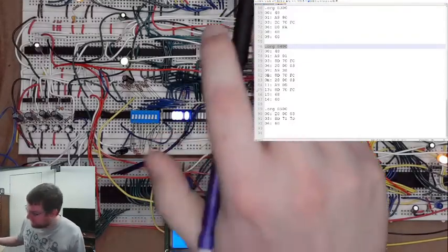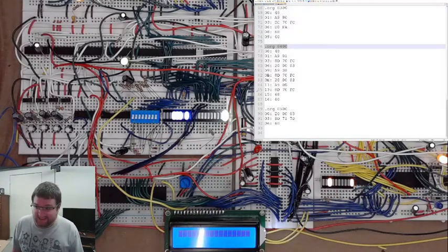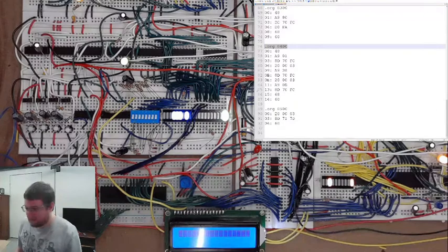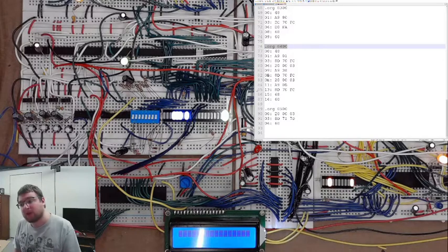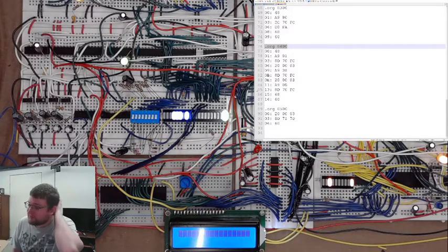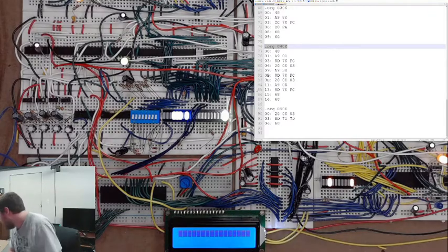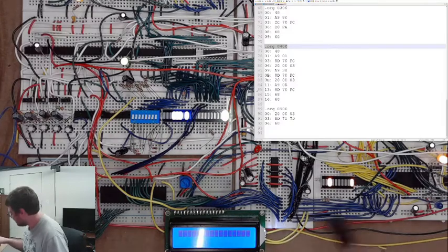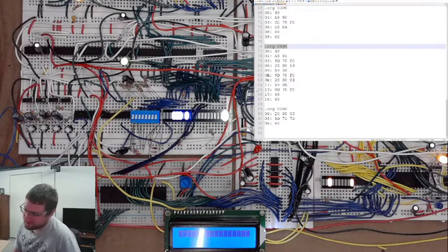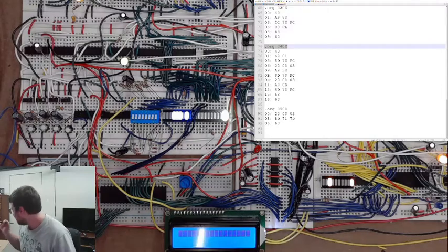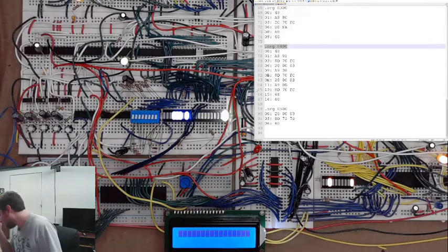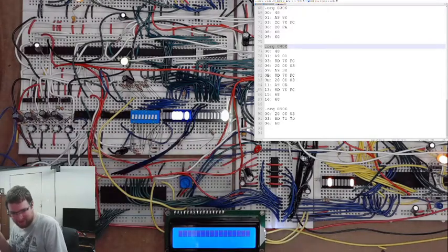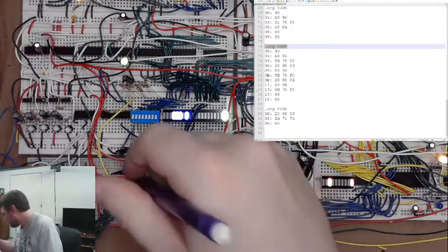And that's why I've actually set this up so that I can copy like 16 bytes at a time, so that we can do it a little bit faster to the screen. But we'll see if that ever comes to fruition, because that means you have to set up 16 bytes, and maybe not. Where was I? We're at 0400. We are about to write a program. We are at 0. Our RAM's enabled. Our counter is disabled. Load disabled. We're good to go. Let's get to writing.